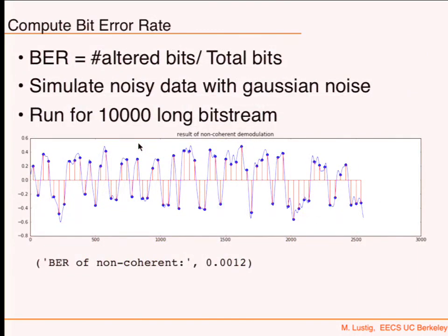Okay, the next thing you're going to look at is what happens when you add noise. When you add noise, then your NRZ signal is going to look like that. Okay, so this is with noise. And you can see why digital communication is so robust. It is so robust because even though we have these huge distortions of our signal, which would have really cost a lot for analog signals, you still have the nice transition here between being positive and negative. You have this gap of resiliency.